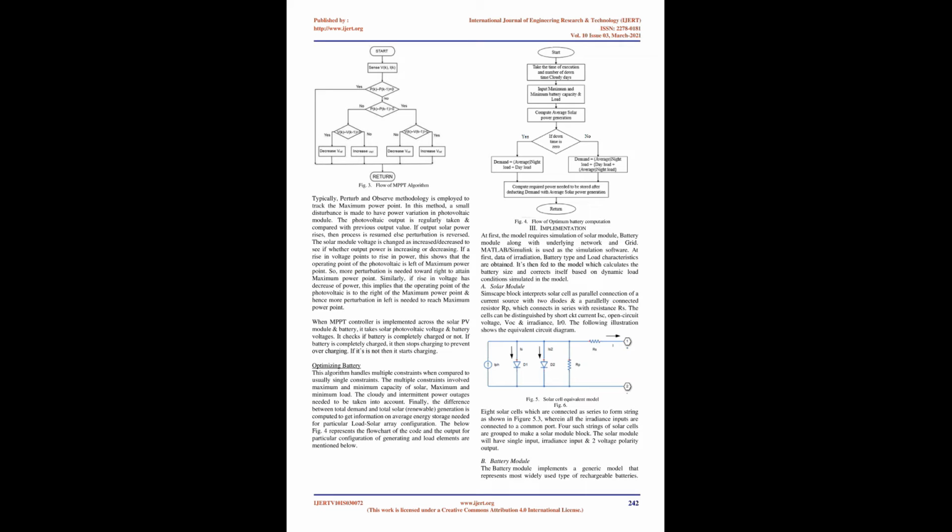Voltage regulators change voltage parameters, to adjust voltage at nodes to be within standard limits. Some of the primary feeders have inline transformers so as to supply business customers. Smaller transformers called service transformers supply house customers at 230V. A distribution feeder supplies one-phase, two-phase, and three-phase loads depending on the customers, like residential users as well as industrial customers.